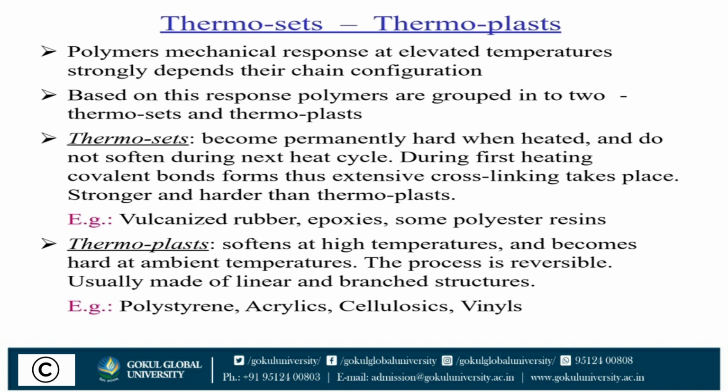Thermoplastics do not become hard with the application of heat and pressure, and no chemical change occurs during the process. They remain soft at elevated temperature until they are hardened by cooling. They can be remelted repeatedly by successive application of heat. Some common thermoplastics are PVC, polyvinyl chloride. The basic difference is that a thermoplastic can be remolded, while a thermosetting plastic cannot be remolded.